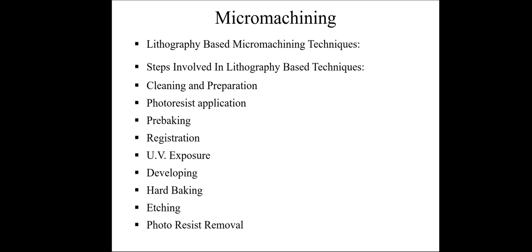Modern ICs are processed exclusively using dry etching, which involves the use of chemical reactants in low pressure system. In contrast to the wet etching process, dry etching allows for a high degree of directionality, resulting in higher anisotropic etch profiles. Also, the dry process requires only small amount of reactant gases.